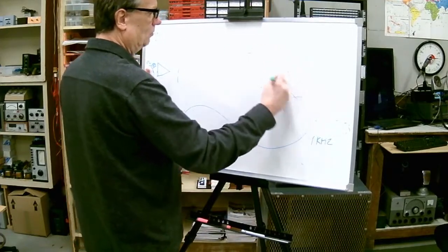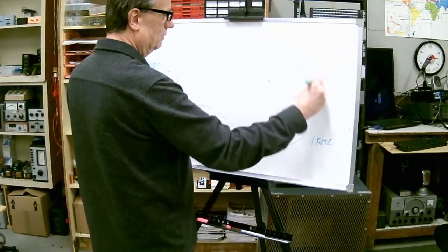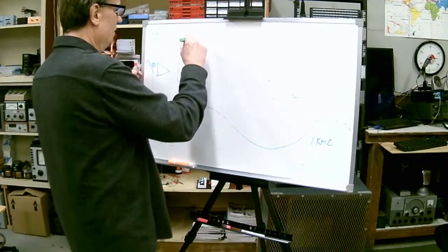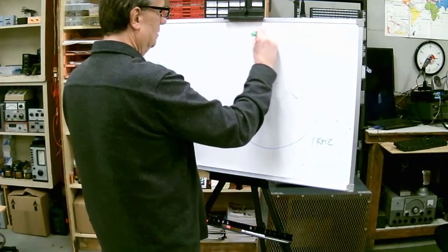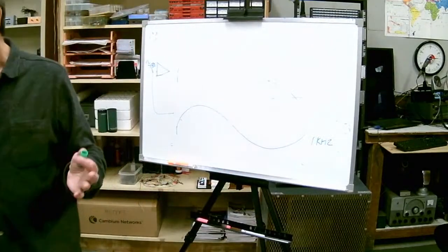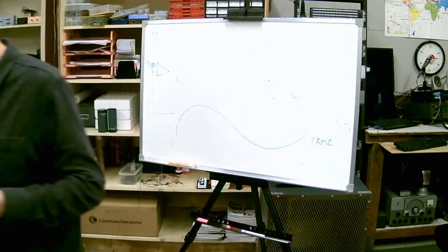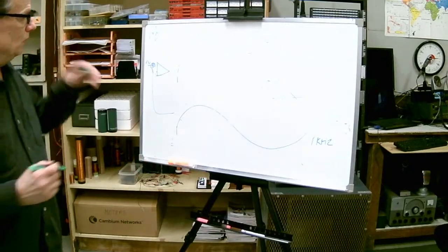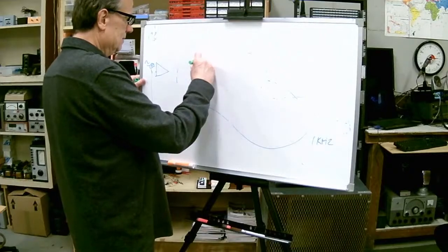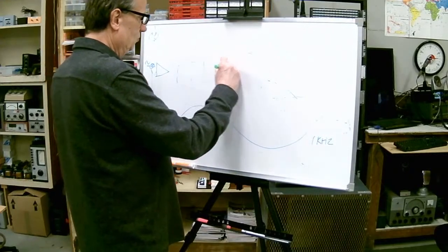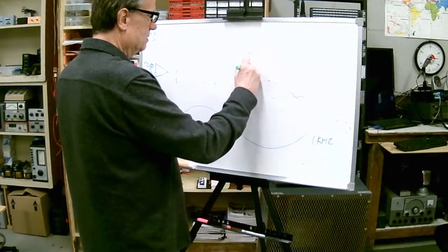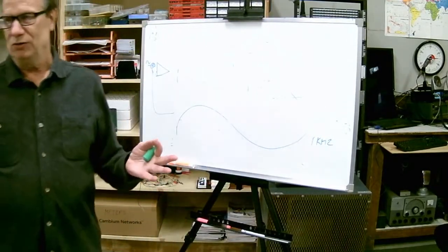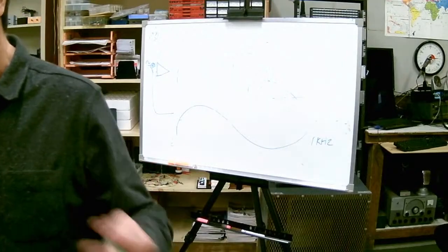So the sine wave is the fundamental for any repetitive oscillation. No harmonics by definition. Harmonics are multiples of the frequency, so any distortion of a repetitive wave will always be harmonic distortion, which means addition or subtraction of harmonics. A square wave is a fundamental wave plus every odd harmonic. So an odd harmonic is 3 times the frequency, 5 times, 7 times.